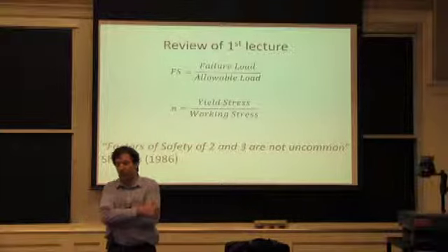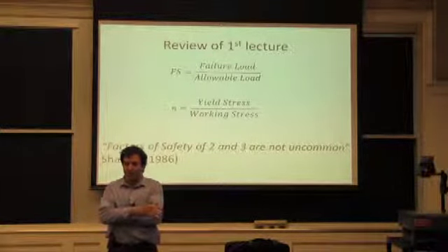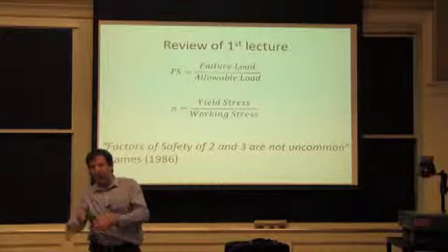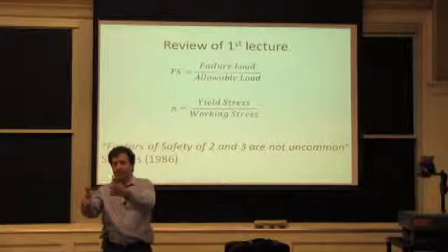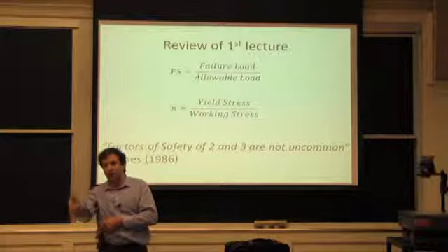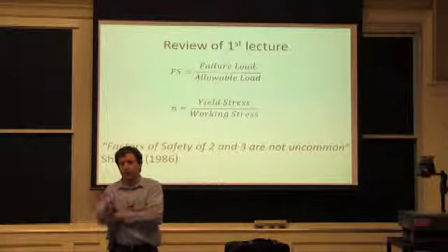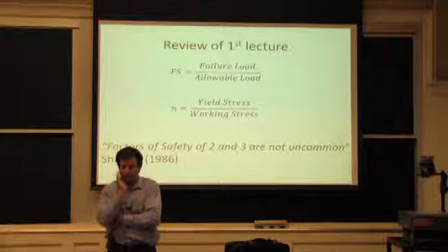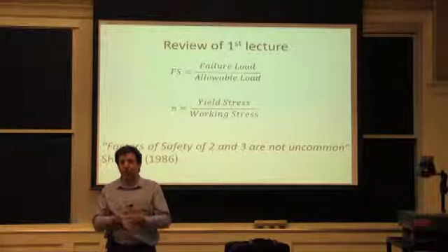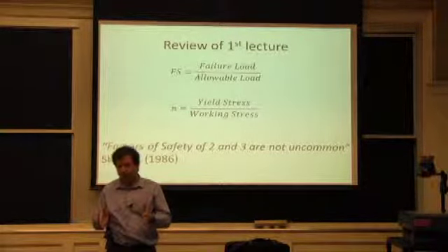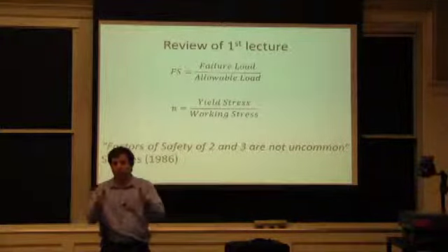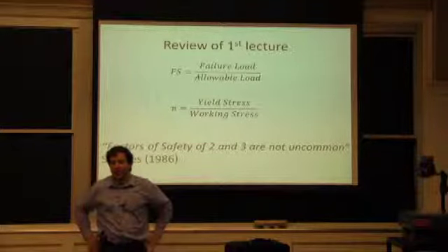The code that governs the design of the elevator says you don't have to put the weight further than, say, halfway on one side. So you say, I'm going to put all the weight halfway, as opposed to putting it on the edge. But in the case that we were looking at, somebody came with a forklift, fully loaded. That was much lighter, with a much smaller wheel span, so they were able to put all the load on one side as opposed to more or less in the middle, and that came to be a problem.